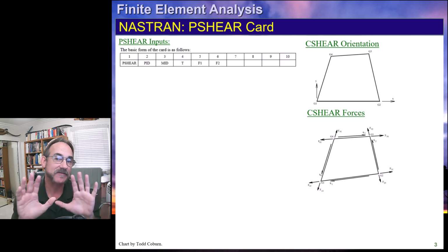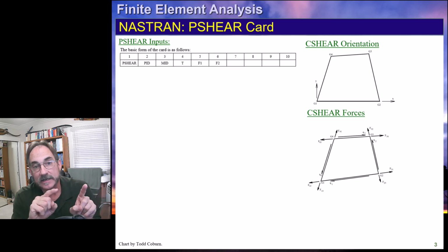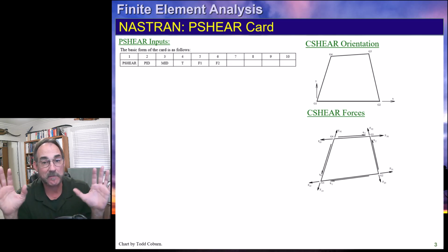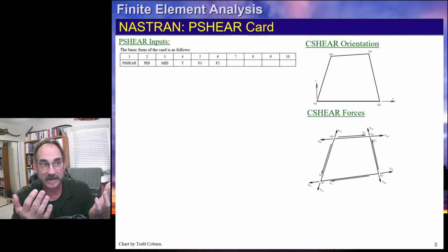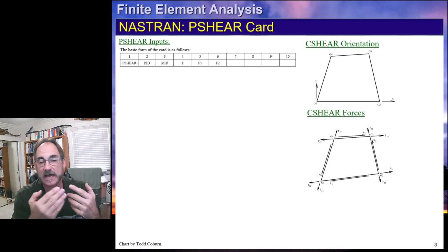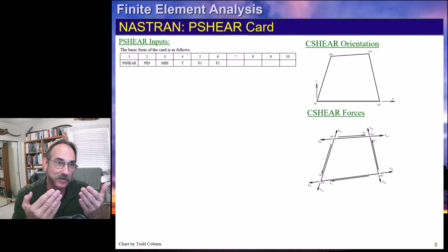If you understand this idea of effective width of skin, then you're probably going to be tickled with the C-shear element, because where a C-quad element is fully effective, all of the skin is giving axial area for any C-quad, and the only way to adjust that is to model your effective thickness as being different, which changes all the capabilities of that element. A C-shear element, you can define how much effective skin is acting with the edges, with the corner members, the edge axial members.